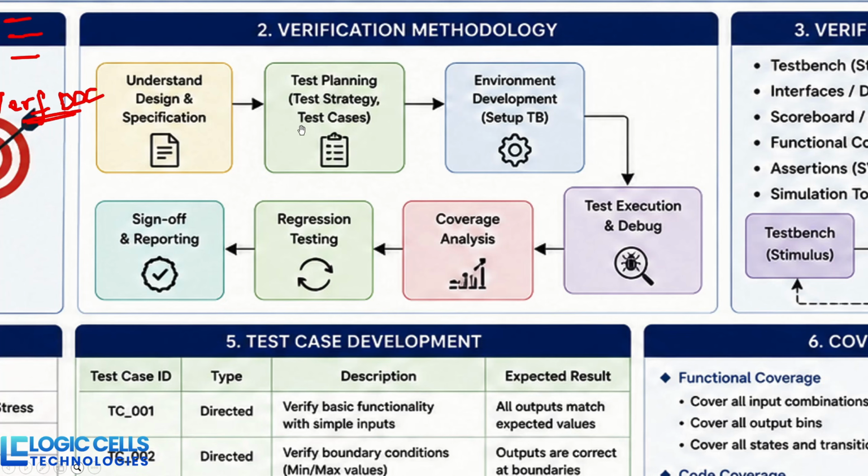Then the different test cases that we perform will be executed in a regression. Regression means all the different tests we perform can be run weekly or bi-weekly in a regression run that will take different randomized data every time. So you will check rigorously that in all possible cases your test will pass. It may fail in any one of the regression runs. Then you need to catch hold of the bug in that case.